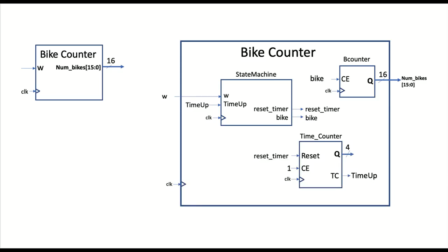Okay. If you have an input port and you don't want to use something, you need to be a little bit careful. Sometimes you can get away with leaving it blank, and sometimes you can't. I'll give you an example. If you're using your 15-bit counter and you never want to use the load feature, you need to set the load to 0.